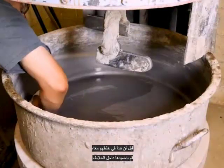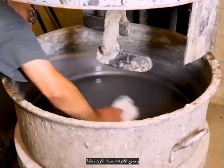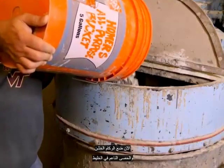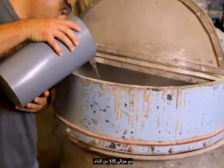Before you begin mixing, dampen the inside of the mixer and all of the tools so that they are wet without leaving any standing water. Now put the coarse and fine aggregates into the mixture with about 1/5 of the water. Allow these components to mix for about 2 minutes.